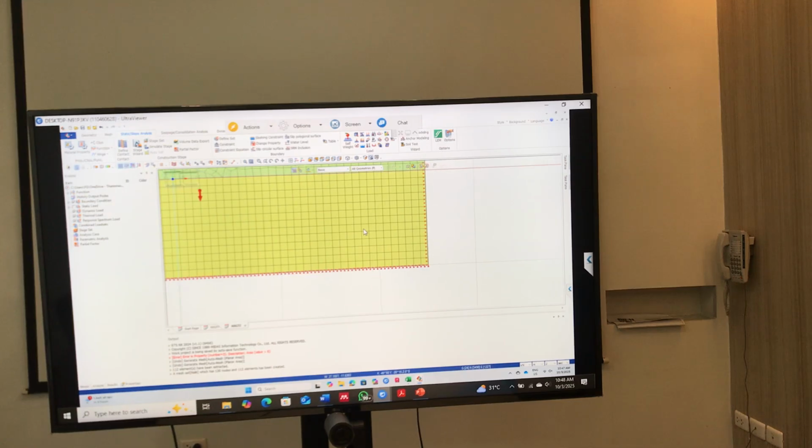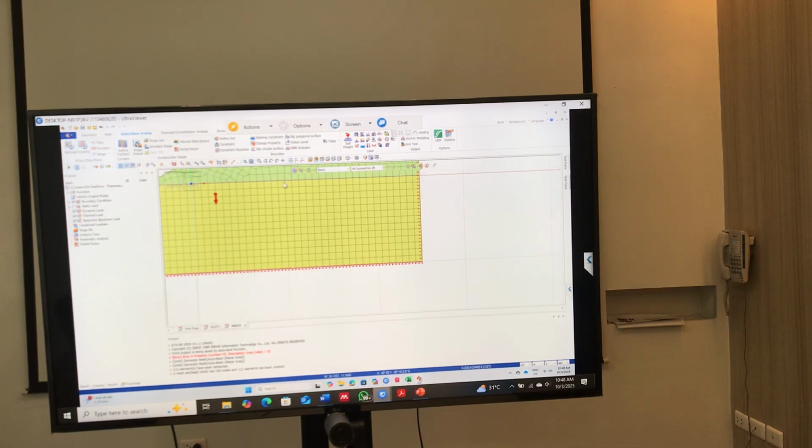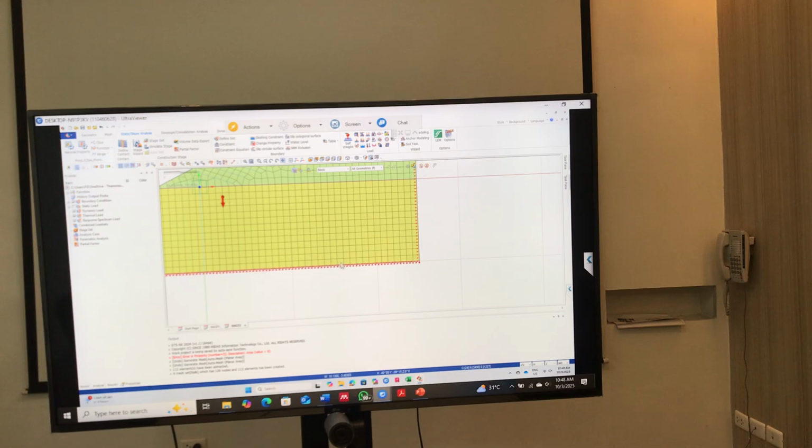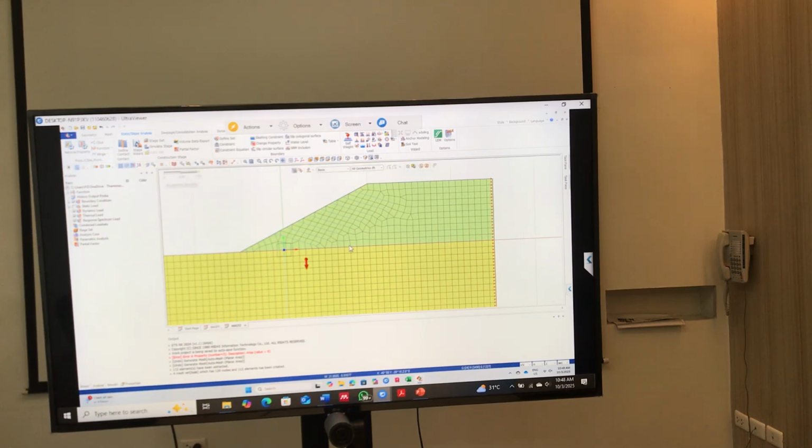If there is a water level, then do we need to make the lateral boundaries restrict water drainage? You understand what I'm saying? Yes, actually, that's one of the questions they also asked me about. Now when we put this kind of boundary conditions, do they also apply to water? No, it is just movement, not water. So that means this kind of boundary means the water can go freely, right? Yes, but in real conditions, it's not like that. So how can we simulate real conditions?